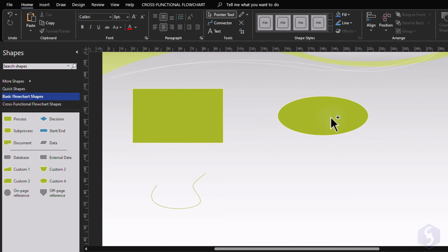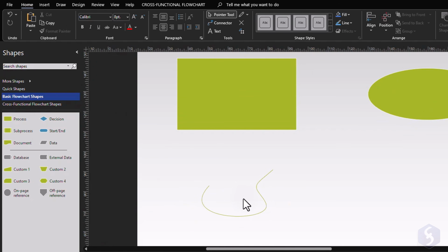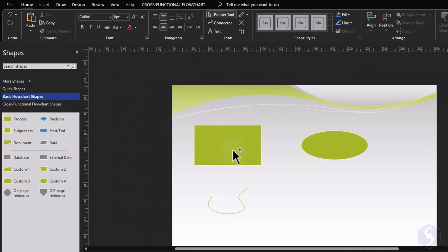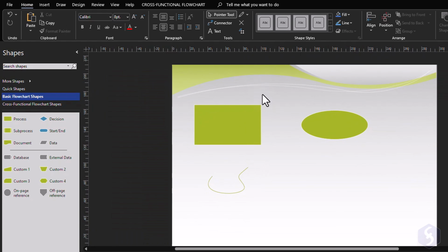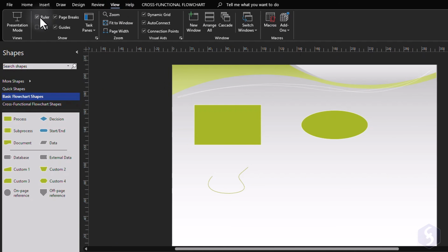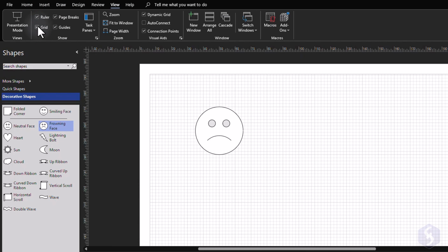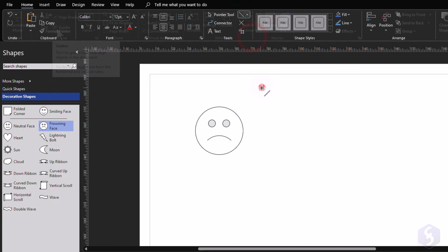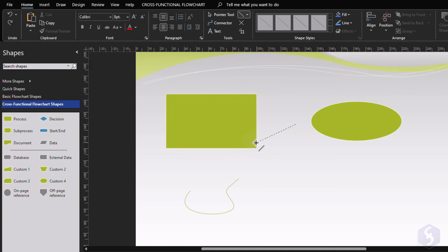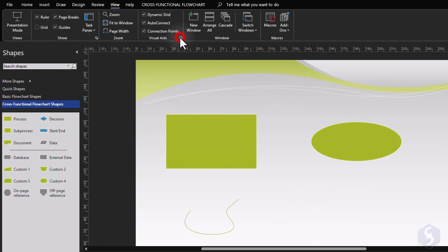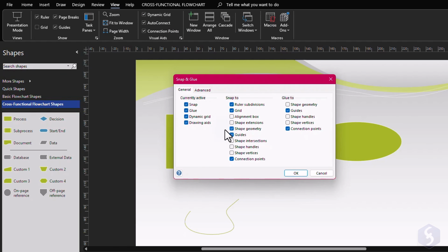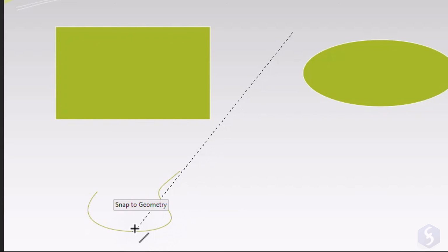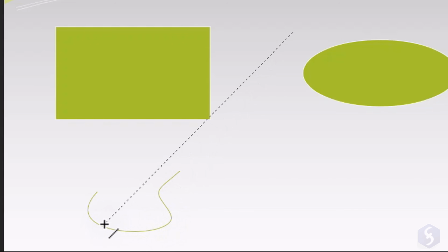Make sure to check your project in detail by zooming in and out with your mouse wheel while holding down the Control key. Visio includes several drawing aids to help you with your drawings. From the View tab, you can enable rulers on your page, page grids, or guides used to follow horizontal and vertical directions. You also get snappings to object points, curves, or the page grid itself, depending on what you set on visual aids above. You can also disable snappings by holding down the Alt key.